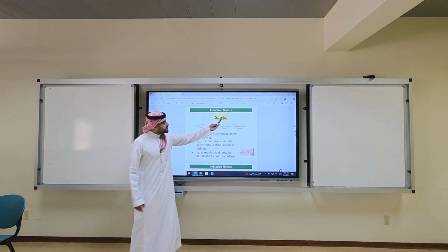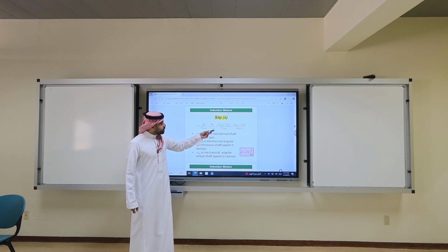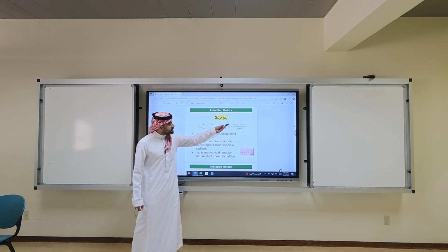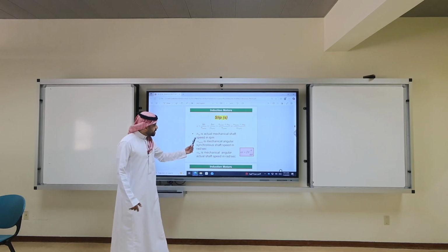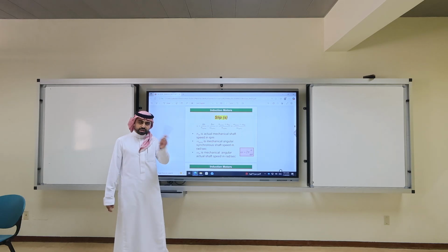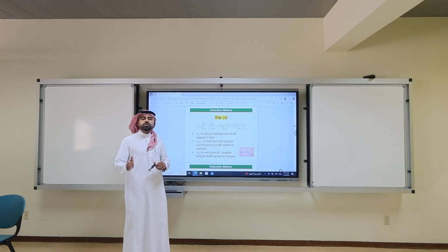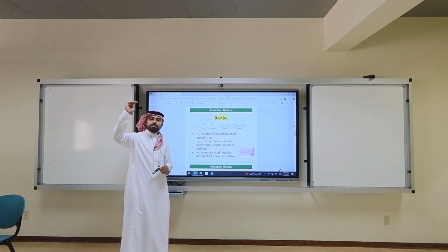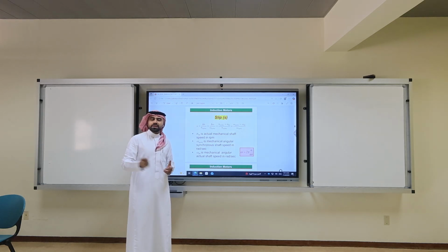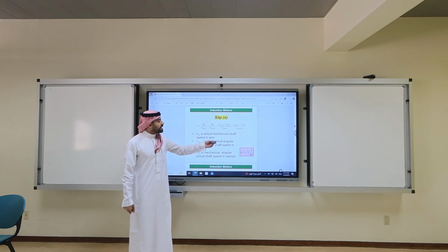The other component is the slip, which is delta n over n sync, or delta omega over omega sync, which is n sync minus nm. What is nm? Nm is the actual mechanical shaft speed in RPM, not synchronous. This is usually slightly less, so if it's 3600, maybe it's 3580 or 3590, depending on the slip. 2%, 3%.